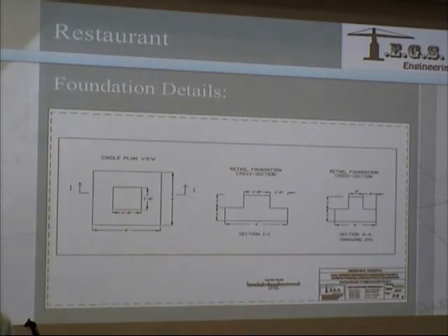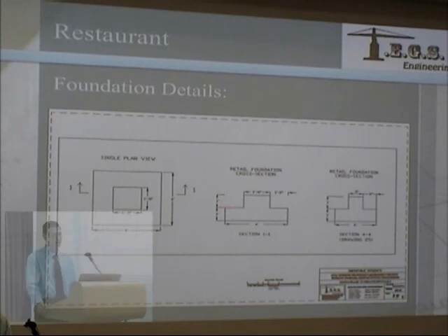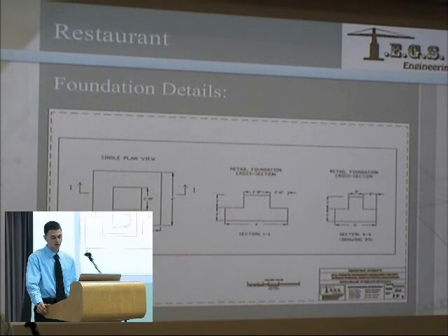These column footings will be 4 feet by 4 feet, with number 4 bars spaced at 12 inches for steel reinforcing. These footings will sit above the minimum frost depth permitted by ASCE 32, since the footings will sit on free draining soil and the exterior walls will contain the proper insulation.